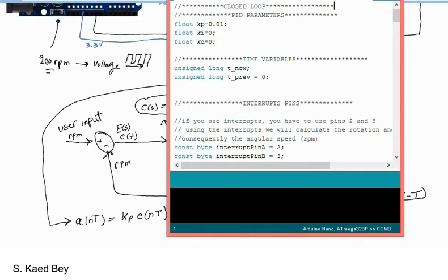The way the trial and error method works, first we set the integral and the derivative terms to 0, and we pick an arbitrary value of Kp and check the response. We have to make sure that we are almost getting what we would like to get, and after this we start tuning the Ki and the Kd values until the system reaches the desired oscillatory behavior.